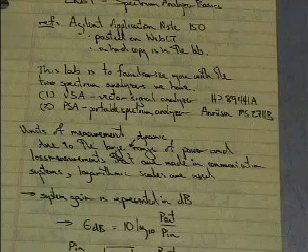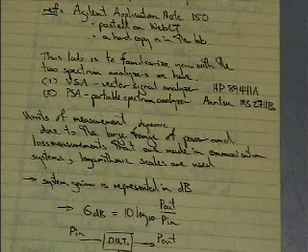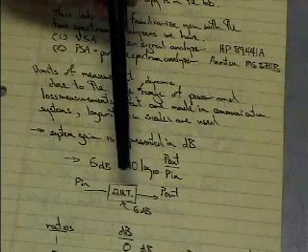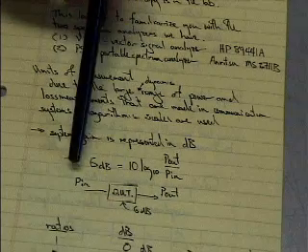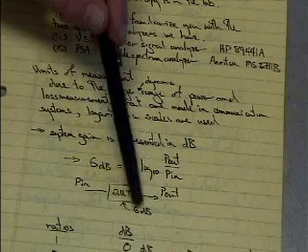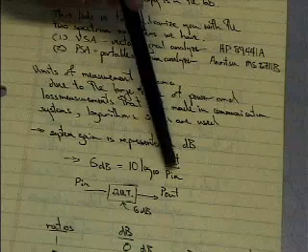To give you an example of the two different types of measurements we may be talking about, we have system gain. Here is a block diagram: a device under test, a DUT, power coming in, power coming out, and what is the gain? We calculate that in dB as 10 times the log base 10 of the ratio of the power out to the power in.